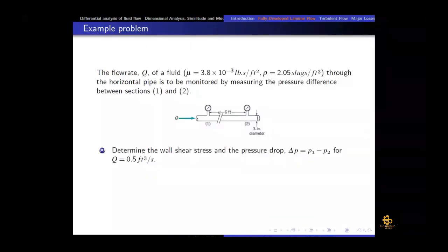So now we need to consider the contribution of turbulence, right? Because most of the cases usually have some kind of turbulence in the pipe flow, because the Reynolds number is usually more than 4,000 or so, and they are kind of turbulent flow.